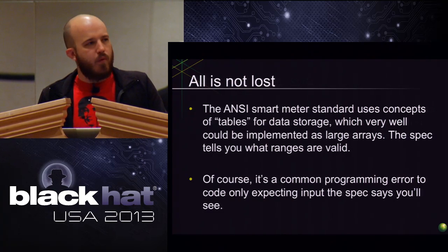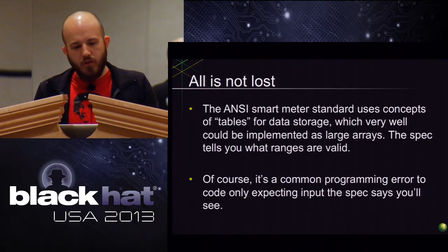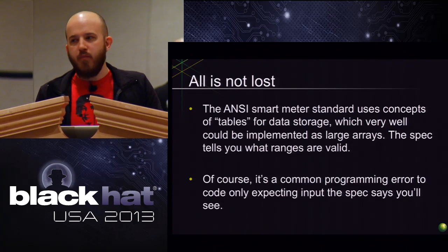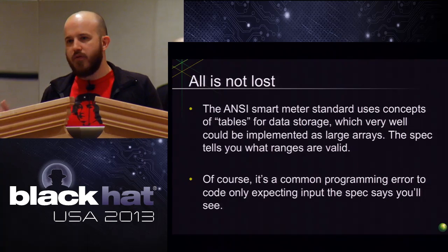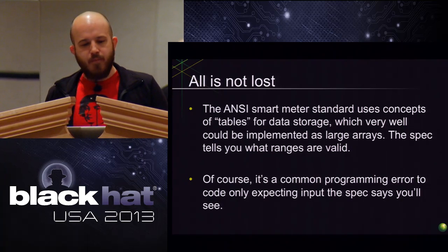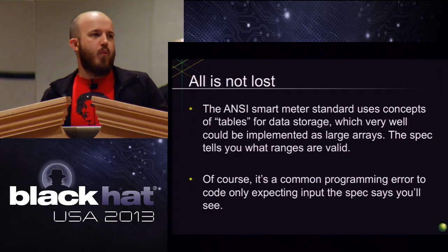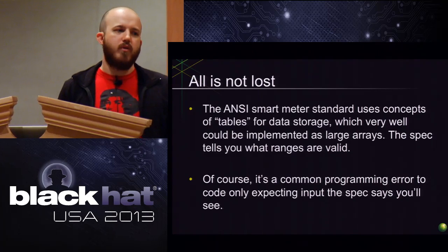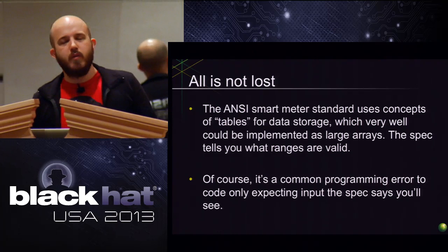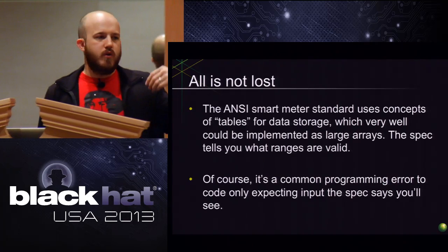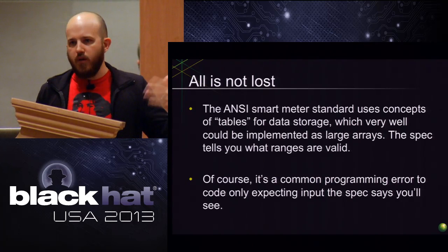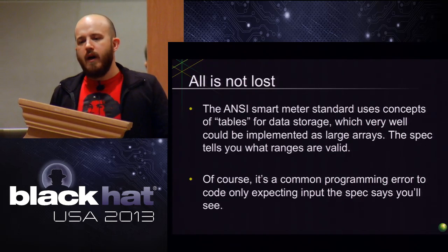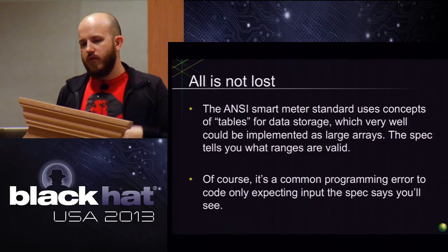But let's talk about the ways that you might be able to do this, and the ways that we'll demo here in a minute. The ANSI smart meter standard uses the concept of tables, right? If you saw Cutaway's talk, you know all about this stuff. When you're reading memory off of a meter, let's say you want to know how much power has been used over this period, via the standard you ask it the right way: hey, give me the contents of table 10, whatever. And if you've got access rights to do that, it'll give it to you.